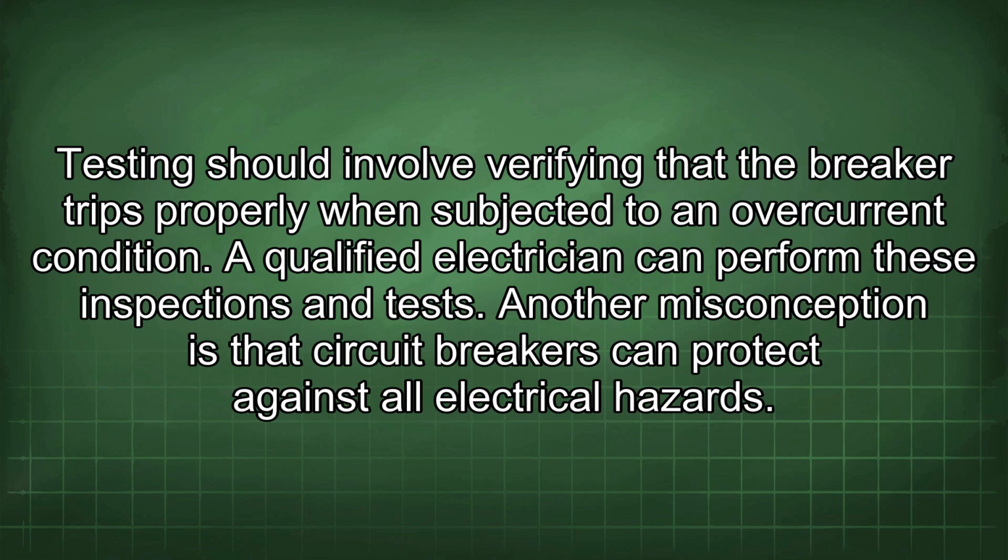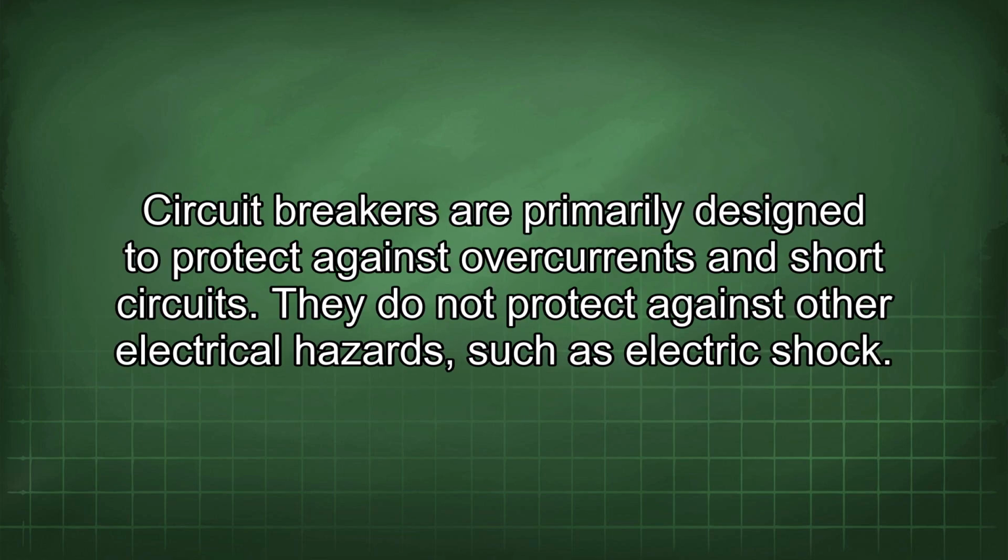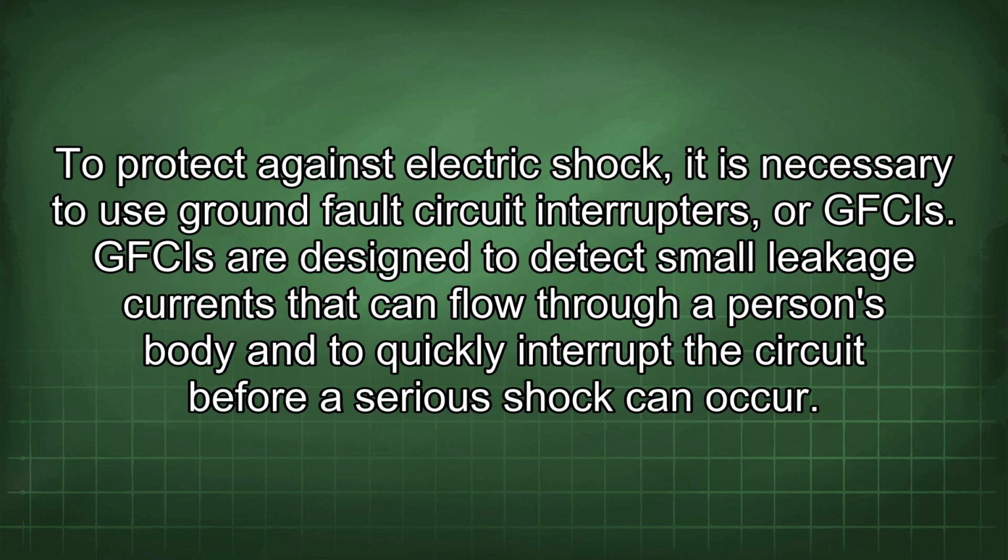Another misconception is that circuit breakers can protect against all electrical hazards. Circuit breakers are primarily designed to protect against overcurrents and short circuits. They do not protect against other electrical hazards such as electric shock. To protect against electric shock, it is necessary to use ground fault circuit interrupters, or GFCIs.